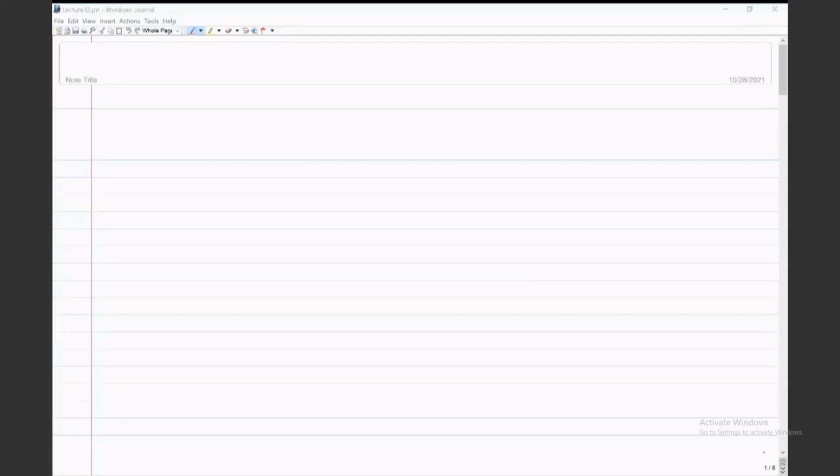You have to do curve fitting. You have to minimize the difference between the experimental data points and the one predicted from this Prony series. So you will get sigma xx as a function of t equal to E(t), where E(t) is in terms of the Prony series, into epsilon xx, constant strain. You have the experimental stress versus time graph, and now you have to fit E infinity, E1, E2, tau 1, tau 2, etc. in such a way that the experimental curve matches the theoretically predicted curve.